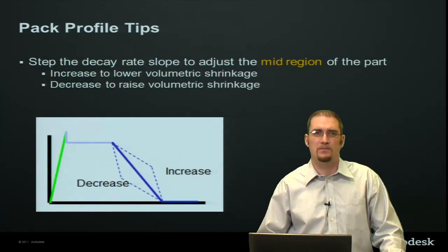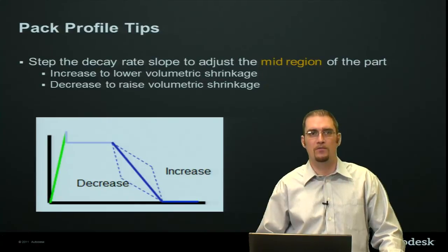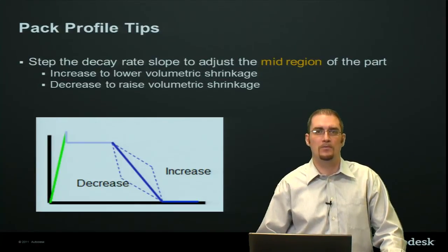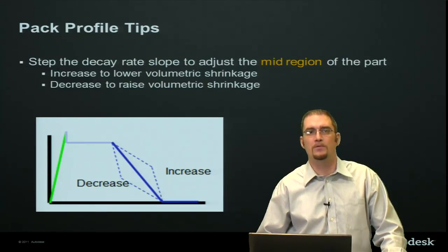Of course, these are just some very basic tips. You can play around with these. As I said, I've played with these over many years. This is what I was taught in my training and learning Moldflow along the years, and it's worked well for me. So I just wanted to pass these on to you in an effort to help you optimize your pack profile.